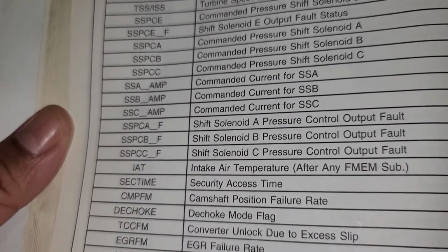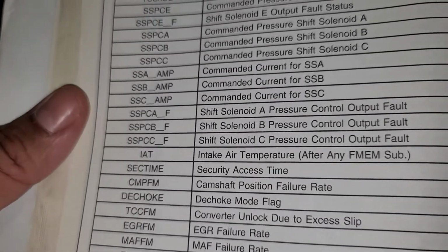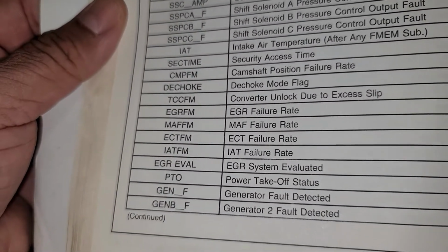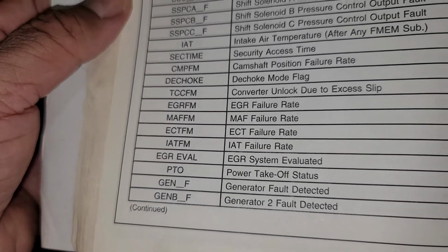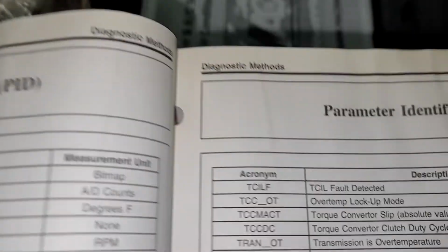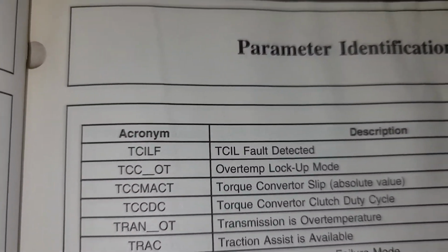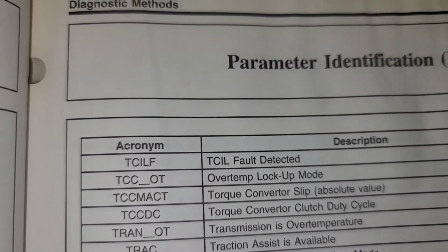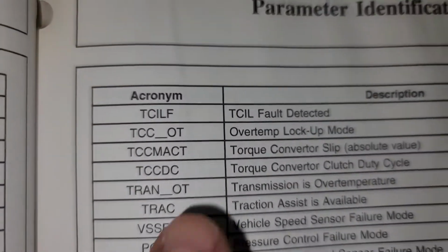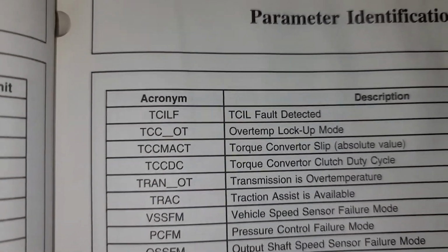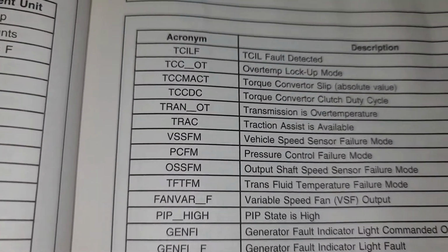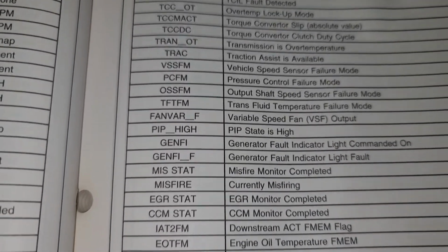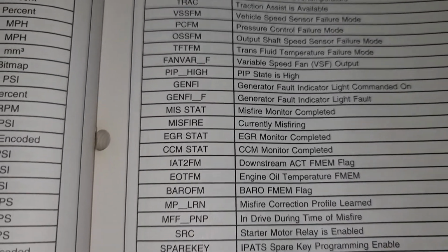Yeah, can you imagine looking at an IDS or a scan tool? The little code reader that I showed you had data. Now with all these PIDs, for different faults that I see on these trucks, there's different PIDs that I got to bring up and monitor, and they're all important. So imagine having a little grid, and all you're seeing is these numbers, these letters, and you just got to pick all the right ones so you can monitor your data. It's crazy. EGR. What else we got here?